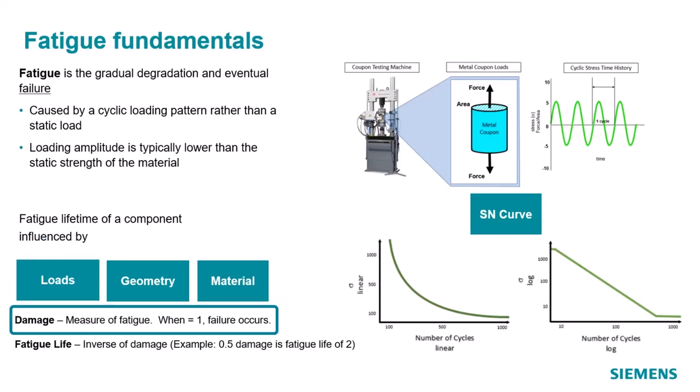I also use this term called damage, which is a measure of the fatigue. And we will see later that when this damage equals 1, that is when the failure occurs.